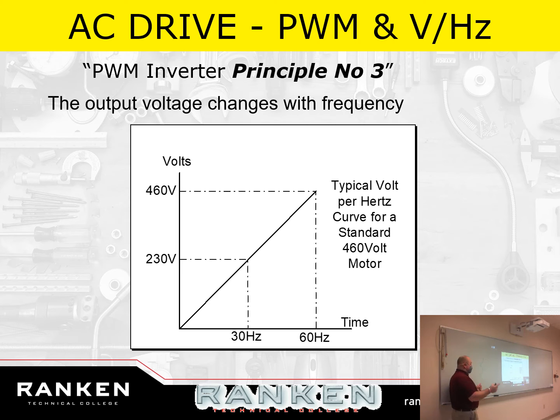And then you do the same thing to T2, because it's got 2 different IGBTs, a positive one and a negative one. And then you check T3, positive and negative, both polarities. It should go overload one way, and it should go basically 0.5 ohms, very little resistance, the other direction. If that's not the reading that you get, the IGBT is bad, which means the drive is bad.